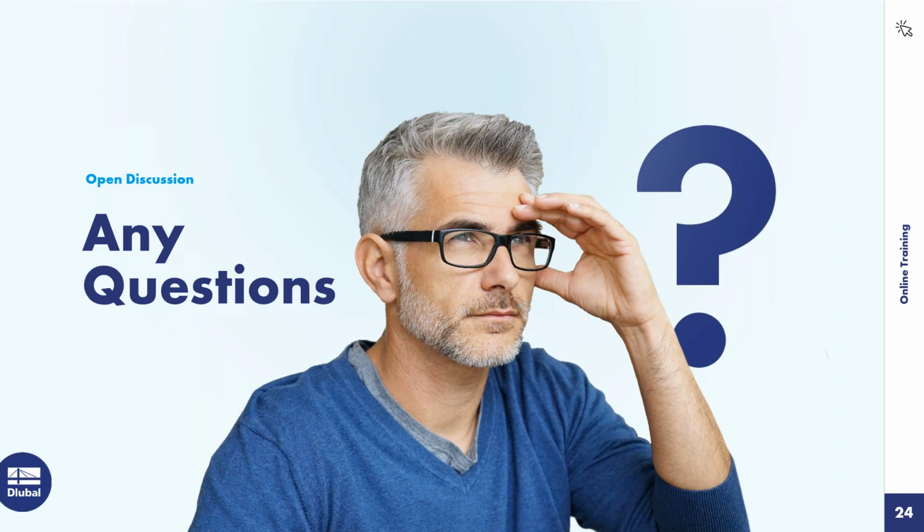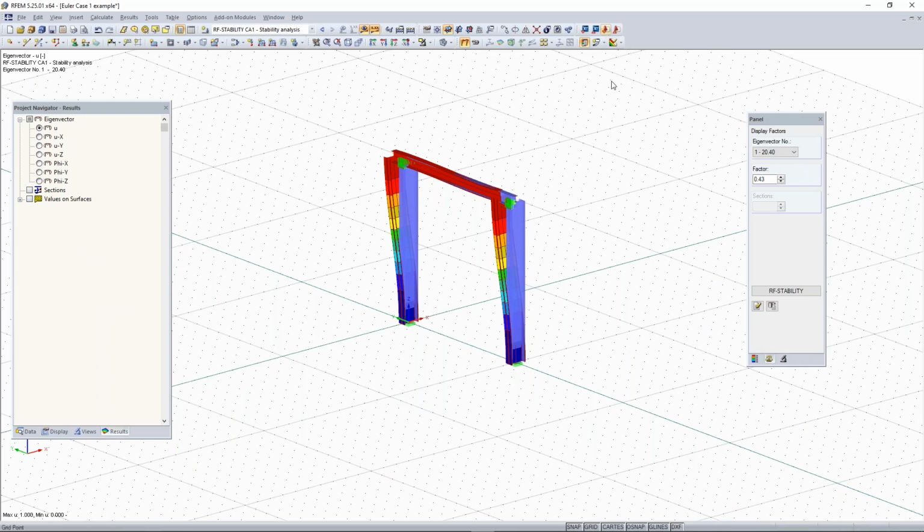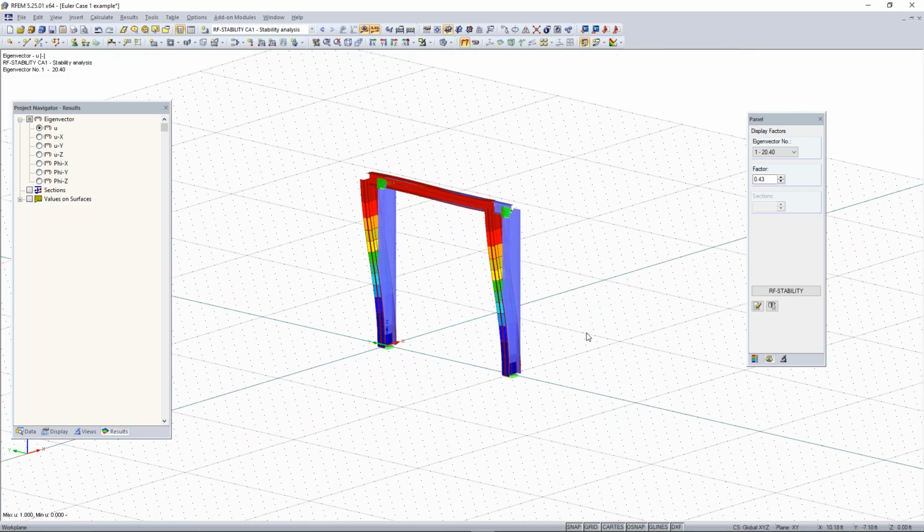Yeah, so we do have a direct integration method with AutoCAD. So if I go back to RFEM, you can import models in from AutoCAD, and so things like center lines are imported as a .dxf file, and if you're integrating line elements like center lines, then that works great. Then you can save the cross-section name and material to those lines in the layers in AutoCAD and have those come over as members.